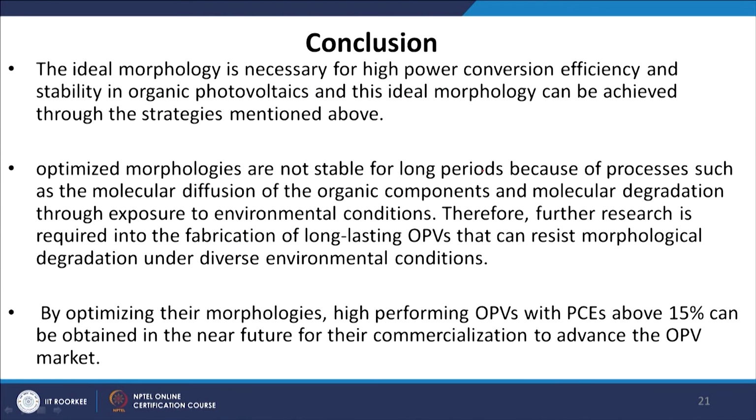Optimized morphologies are not stable for long periods because of processes such as the molecular diffusion of the organic components and molecular degradation through exposure to environmental conditions. Therefore, further research is required into the fabrication of long lasting OPVs that can resist morphological degradation under diverse environmental conditions. By optimizing their morphologies, high performing OPVs with PCE above 15% can be obtained in the near future for their commercialization to advance the OPV market.